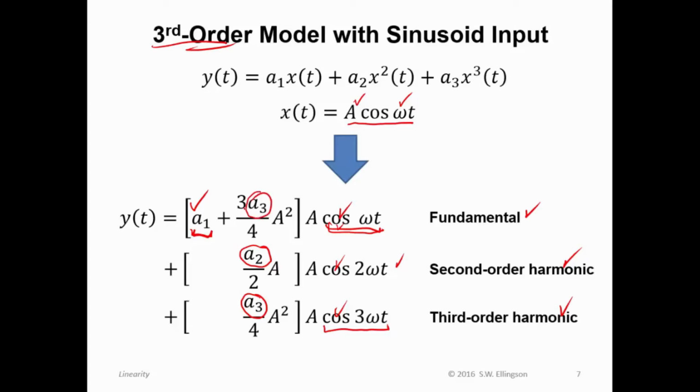So interestingly, when we have a third order model and we apply a sinusoid, we see that the fundamental depends not just on the linear response, but also on this additional term, which is dependent on the value of a sub 3.